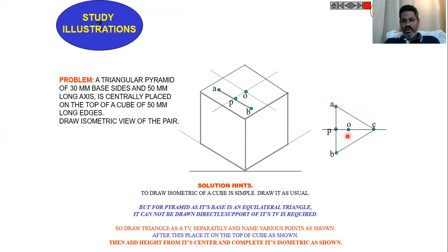After locating the O point, locate AB at a distance from point O, perpendicular to this line. Then get the compass and locate the C point by using the compass. Then join this point and A, and name that point C. Join AC and CB like this.